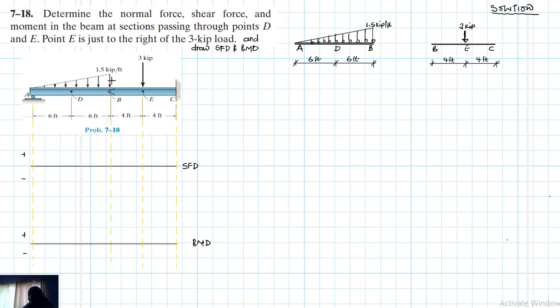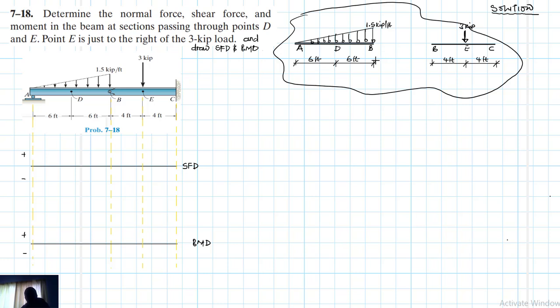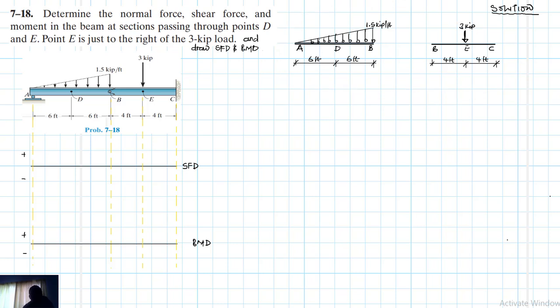It's a continuous beam, roller supported at A and fixed at C, and then there's a hinge pin supported B. So separate it at B, and that's when we can apply the available equations of equilibrium effectively. Okay, so we've done the separation, which I've drawn here in advance, and then we just apply the equations of equilibrium quickly, and then start finding the support reactions. All right.